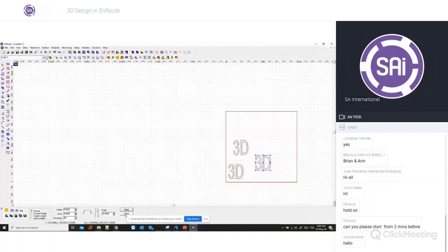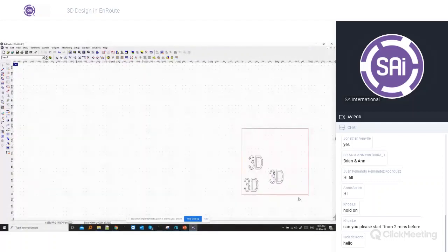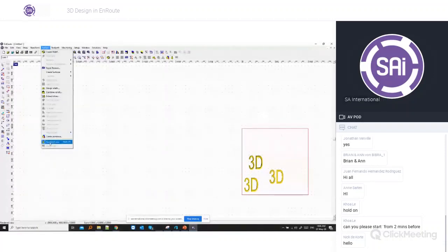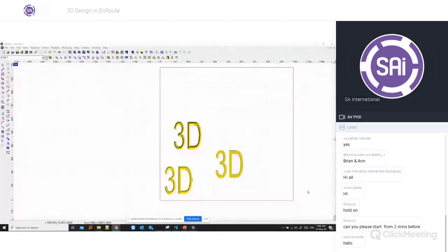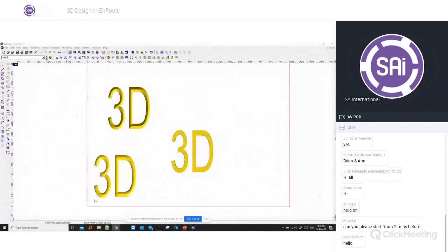And then if we go and have a look in the other views, I will just render everything. Hitting Shift F9 will render your reliefs. You can also do that through the surface menu. So in here we'll have our round relief, our beveled one here, and the flat one in here. By double clicking on the top here,